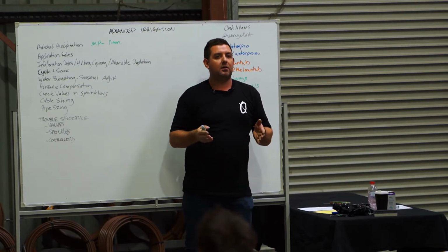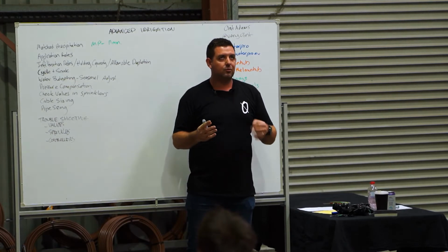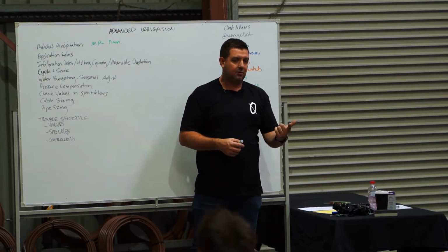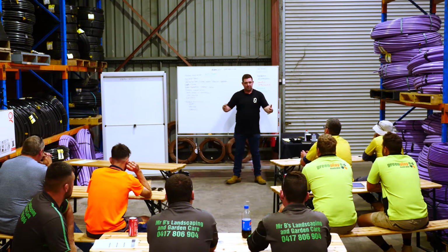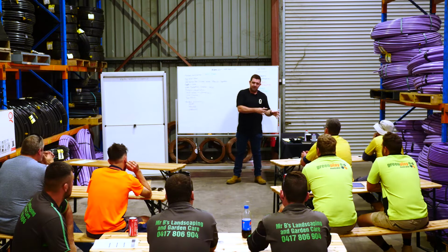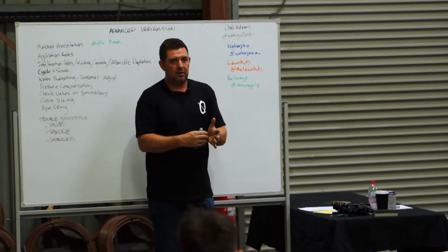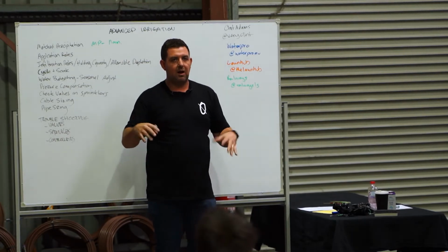You can design the traditional spray systems in a matched precipitation configuration. The thing is, you just can't put, say, a 10A, a 12A and a 15A necessarily on the same line, because they're all putting out different amounts of water. But if you only use 10As and they were like a quarter and a half, you're getting that. So a quarter is half the amount of water as, sorry, 2/4 is the same as a half in that